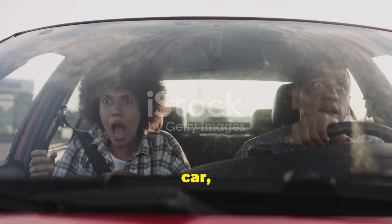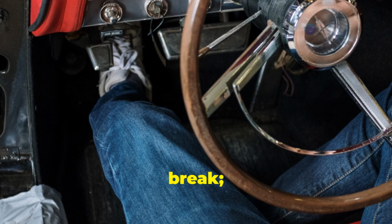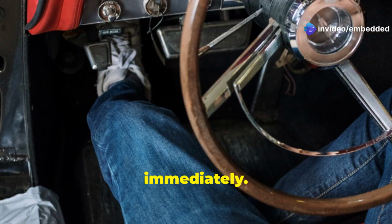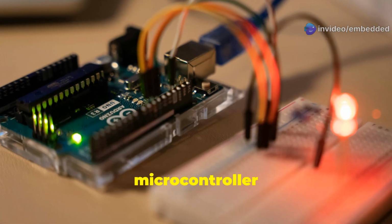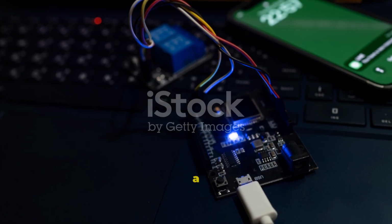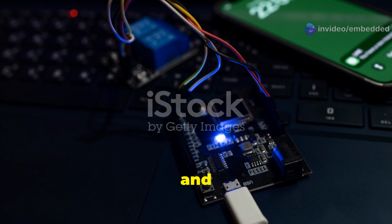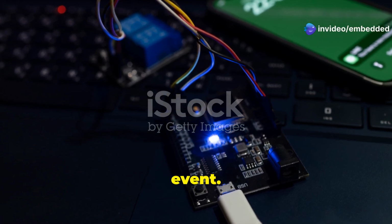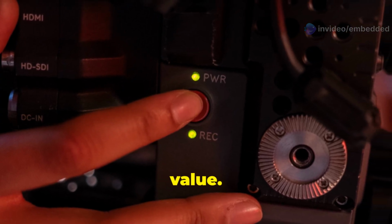Imagine you're driving a car and suddenly you need to brake. You don't wait for a scheduled brake. You react immediately. Interrupts in embedded systems work similarly. They allow the microcontroller to respond to critical events immediately. An interrupt is like a hardware signal that tells the microcontroller to pause whatever it's doing and handle a high-priority event. This event could be anything from a button press to a sensor exceeding a critical value.